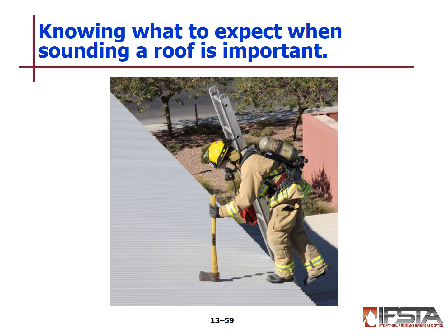Knowing what to expect when you're sounding a roof is important. If it sounds solid or if it sounds weakened, pay attention to the sound. It's difficult to hear at times because there's just so much going on and you're completely enclosed in the system. You can hear yourself breathing and everything else, but you can also feel it. So if it feels solid when you're hitting it, if you're a little unsure, hit it harder.